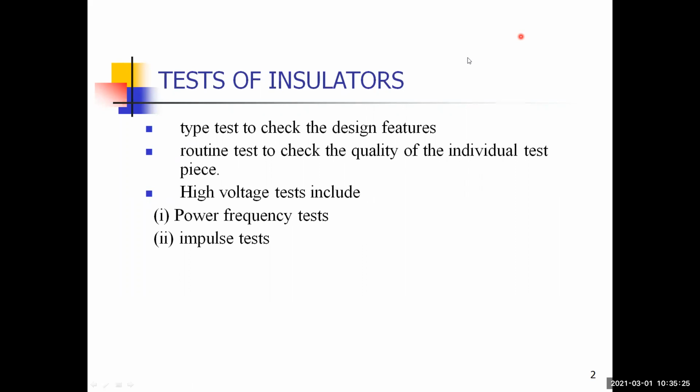For example, in machines, if you do not use proper insulation, frequent short circuits may occur in these machines. So compulsory testing of insulation is required, and then only is it placed at a particular place. For example, a transmission system operates with very high voltages. That's why you have to keep very high voltage withstanding insulators. Then only can the power transmission be done without any interruptions. Otherwise, it is very difficult. So the testing is compulsory.